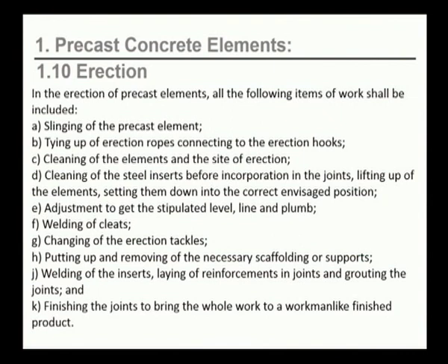The sixth point is welding of cleats. The seventh point is changing of erection tackles. Next is putting up and removing the necessary scaffolding or supports, and then welding of the inserts, laying of reinforcements in joints and grouting the joints. Last but not the least, finishing the joints to bring the whole work to a workmanlike finished product.